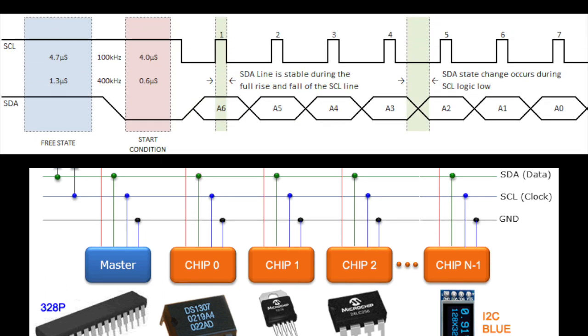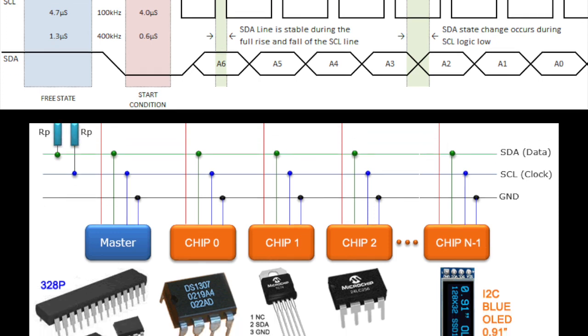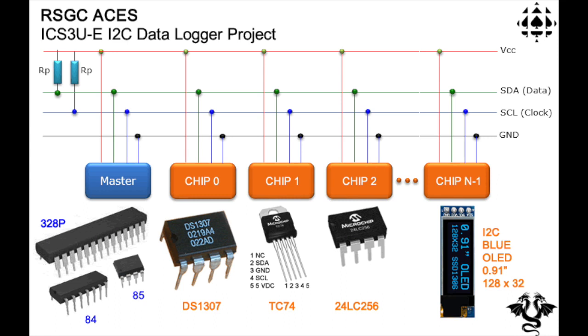The system begins communication with a peripheral by pulling the serial data line low, which is known as the start condition. During this condition, all peripherals listen to the master to hear if their address is being called. The peripheral with the called 7-bit address responds by pulling the data line low, indicating an accepted response.